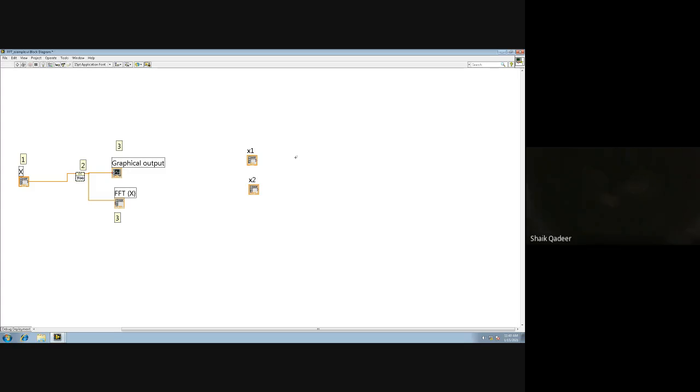Okay, I'm copying from here. Control C, Control V, right? But when we see the help of this function, it accepts only one input and gives the DFT output of that signal. So how can we find out DFT of two sequences? In order to answer this question, we need to separately find out DFT of these two sequences, using two different Fourier transform functions.